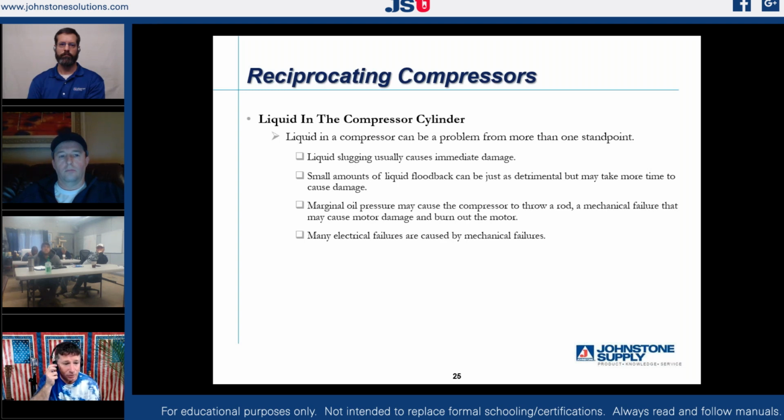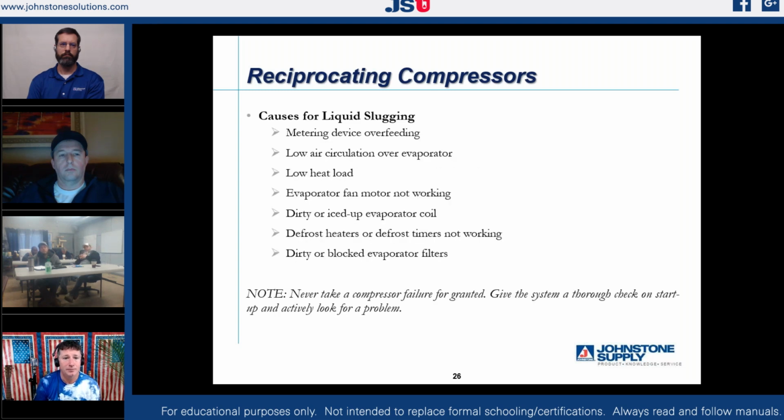So if we think about that, if we're introducing refrigerant into that oil and we're going to cause that oil to foam, our oil pump is a liquid pump, right? It's not a vapor pump. So in these reciprocating style compressors, our oil pump is designed to move liquid oil, not vapor. So when we get that refrigerant boiling inside of that oil, we're actually going to foam our oil and we're not going to maintain our proper pressure.